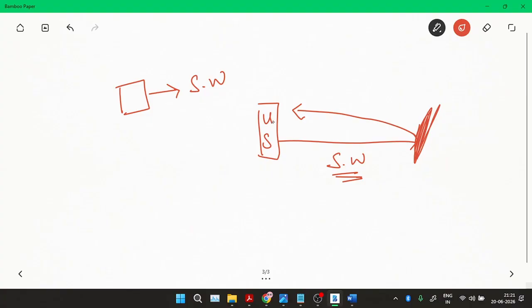You might ask me, what happens if there is no obstacle? Then the sound never comes back, and that way it can say that there is no obstacle. If it is receiving a return sound wave, that definitely means you have some obstacle in front of it. Okay. Now, the next question is, how is it able to calculate the distance? We know that the speed of the ultrasonic sensor's sound waves is 340 meters per second.